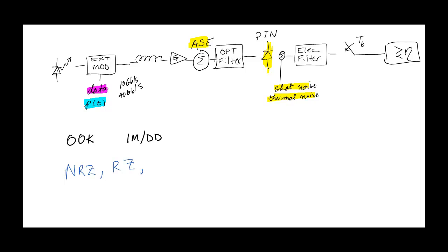The third pulse we'll be using is the root raised cosine, or RRC, with a 30% roll-off factor. The root raised cosine is a very practical pulse that allows us to trade off bandwidth expansion against robustness to timing errors, for instance, robustness to jitter.